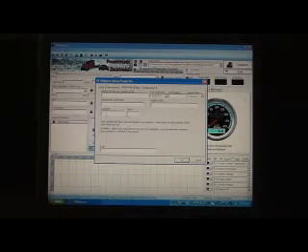The odometer and the hours. OBD2 does not display engine hours or odometer. In this case, you would enter it here prior to connecting, and that way your reports will have the odometer and or hours.